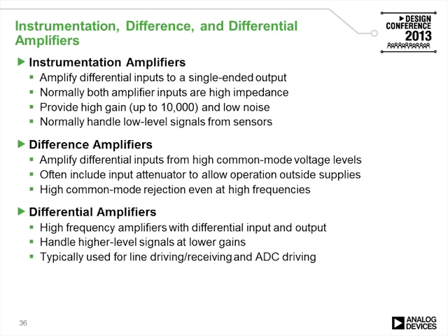To work with differential signals, we have the following amplifiers: instrumentation amplifiers, difference amplifiers, and differential amplifiers. These amplifiers typically take a differential input and amplify it. In the case of instrumentation amplifiers, they also add a lot of gain and can provide high input impedance.